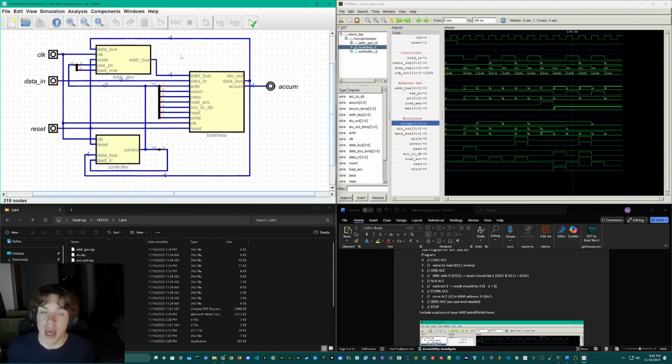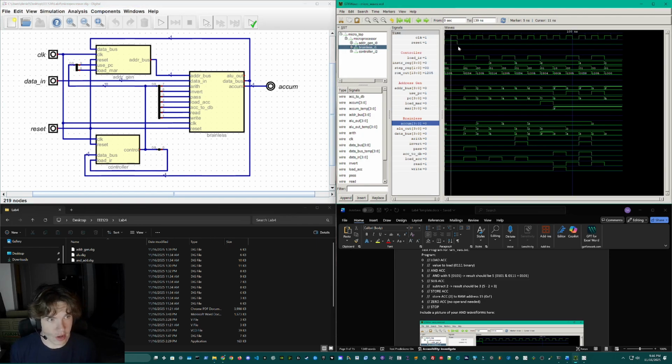And then the 4 new instructions, which I talked about earlier, are and, zero, sub, which subtracts, and store accumulator, and those 4 I've implemented into this one GTKWave simulation here. So I'm going to show these off. We're going to go 1 clock at a time, right? So start at clock 0. At clock 0, we reset the circuit. You can see reset is high here.